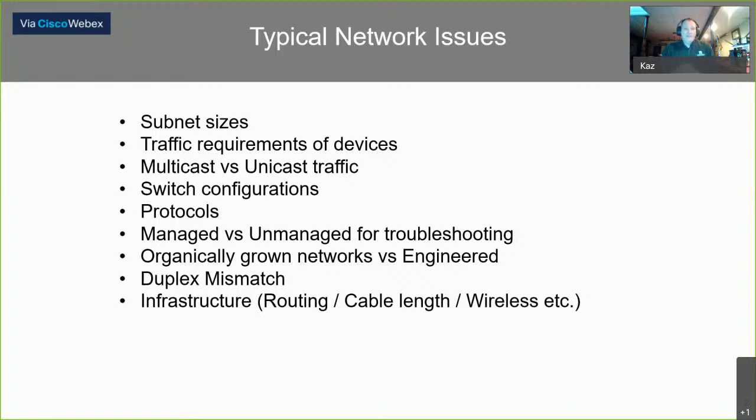And with the advent of the IIoT, Industrial Internet of Things, you see more and more devices that are capable to be on the network, so people want to put them on the network. And they put them on the same subnet. And if you do that, basically, there's a lot of bandwidth taken up in just servicing all of the chattiness that these devices have, talking to each other and to their switches.